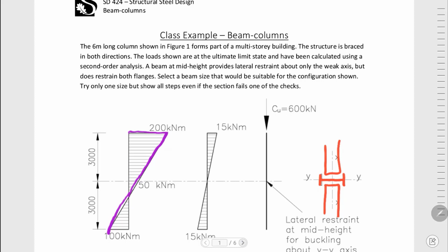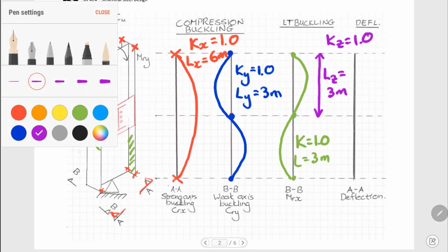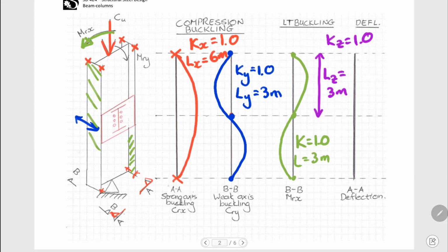So when we plot our deflected shape, the path that it will physically follow, it will look something like this. This is very exaggerated, but something like this. Maybe it wouldn't even pass the axis, but we do get double curvature, and we have some delta value, and this is our deflection or our deflected shape.